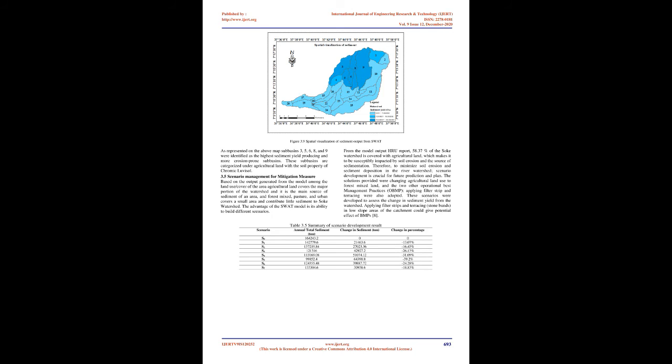The total annual sediment yield estimated by the SWAT model from the river at the outlet during the calibration and validation period was 164,243.2 tons/year. Hence, 164,243.2 tons/year of sediment is generated by the river. The total area of the watershed is 186.64 square kilometers and the specific sediment yield from the watershed is 8.80 tons/ha/year.